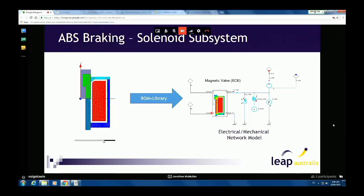So, if you remember, we looked at reduced-order modeling at one stage, where you take a detailed electromagnetic or mechanical system and convert it into something simple. This is what the design process looks like for a solenoid coupled to a valve. So this is our Maxwell model. We did it in 2D axisymmetric. We ran a transient simulation to characterize how it would respond.